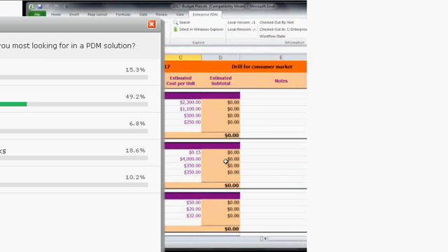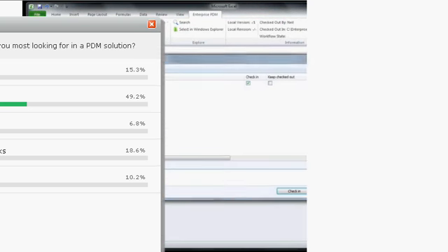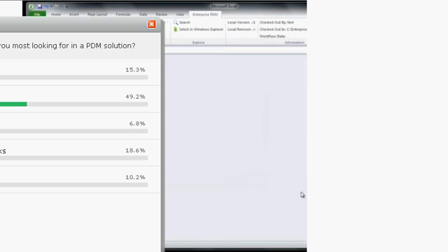The other thing you might have noticed is the project number and names have been automatically added to these cells up at the top. These are linked to the data card, so if I update it in one place, the other is also updated. I'll just modify the name and check the file in right from the menu bar. Make a few quick edits here. Save it, and we'll go ahead and check it in. Even if I forget to check out the file before I make the modifications, I don't lose my changes when I do check it out.